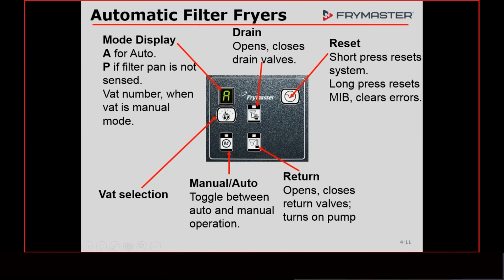If it stays with the position here, meaning we put that actuator over here and we don't have a problem, the problem's with the AIF board that it hooks to. I've had several times where you get that indicator and it's an AIF board. I'm not saying that we have bad AIF boards, but it sticks out in my mind where I've changed an AIF board because of that reason. It wasn't an actuator, it was a board.